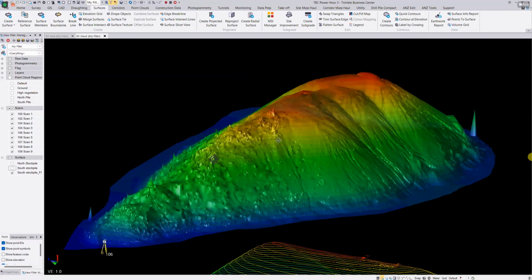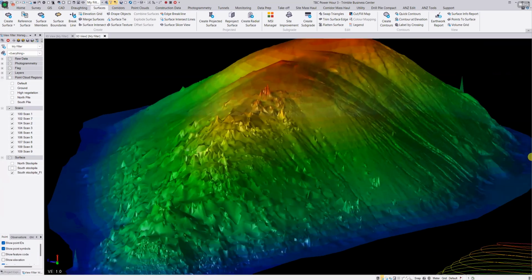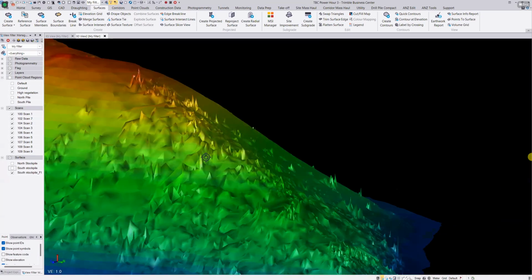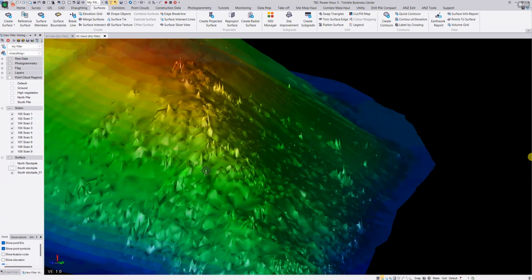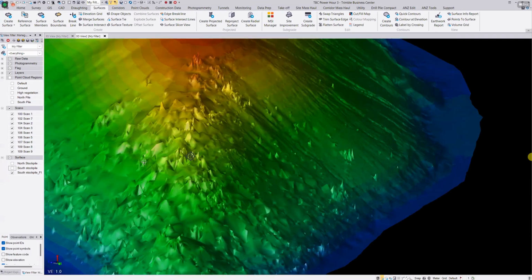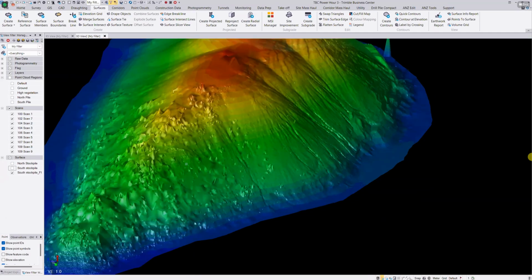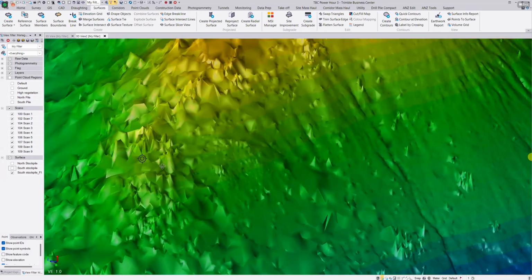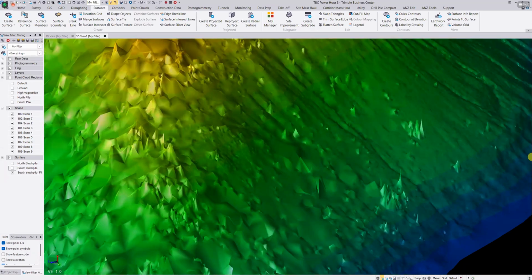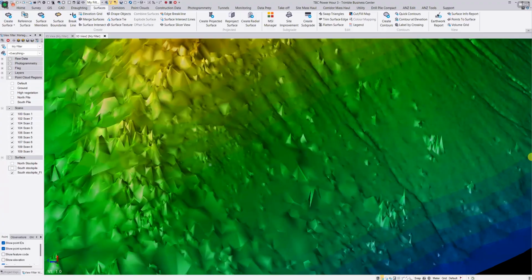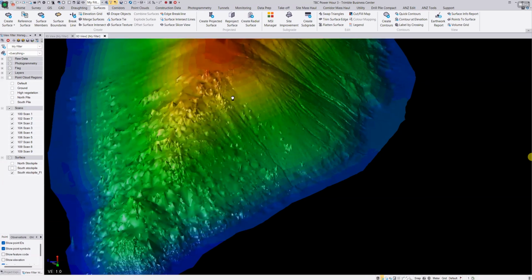So there you go. Quite a lot of the spikes were taken out, the outliers. It's not 100% clear. That is because the vegetation was quite dense around here. So the scanner never picked up the exact ground, or let's say the stockpile, at certain areas. So as you can see over there, it will not know that that is an outlier because the height between this and the point next to it is very close to each other. Where areas where we do have a bit flatter section where we could see the stockpile underneath, it cleared out those outliers much better.